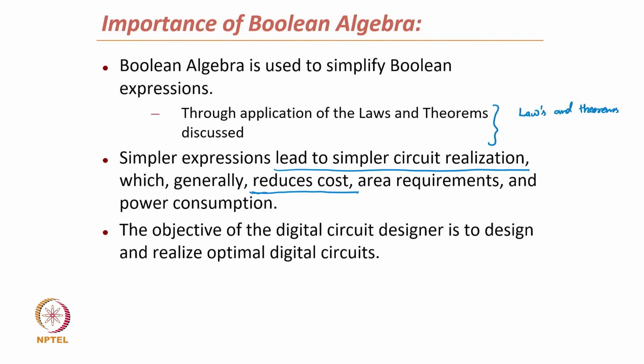The cost is how many circuits we need to implement a single function. If that reduces, the cost reduces. The area requirement also reduces because you need less area to implement fewer logic gates, and power consumption also reduces because you need fewer circuits. The objective of digital designers is to design and realize optimum digital circuits. So, when a digital designer implements logic, the whole intention is to reach an optimum digital circuit.